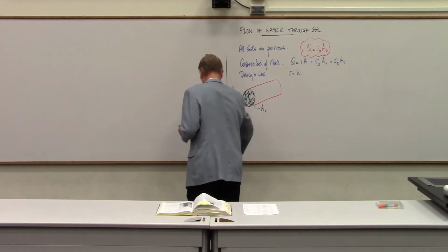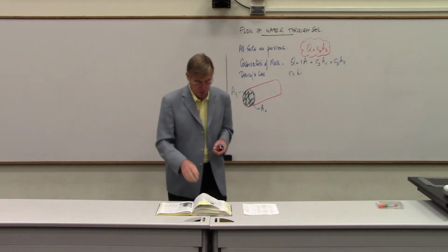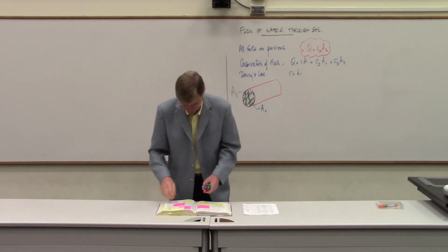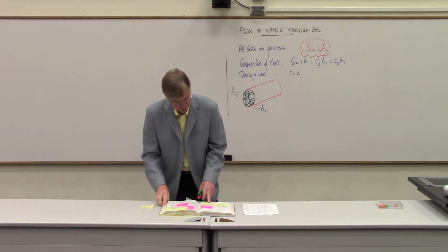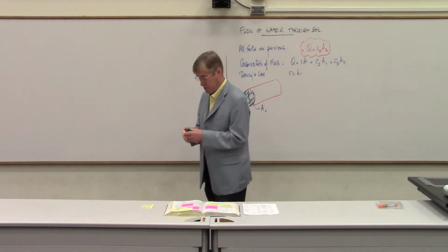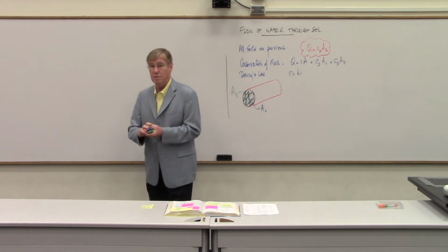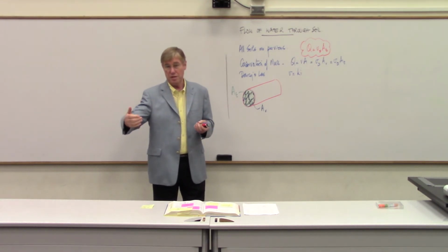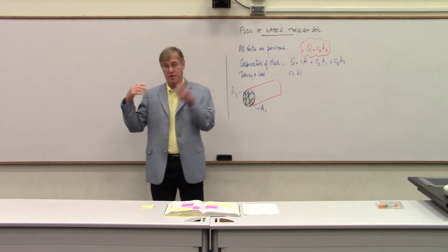Right here. And I want to go back to the Teton Dam. I want to make a cross section of the Teton Dam, and we're going to work all our definitions on that example, because hopefully it's still, you know, that's the dam where you had a leak on the right abutment, and the leak regressed, started to attack the downstream slope, bigger hole, and then finally the dam breached.